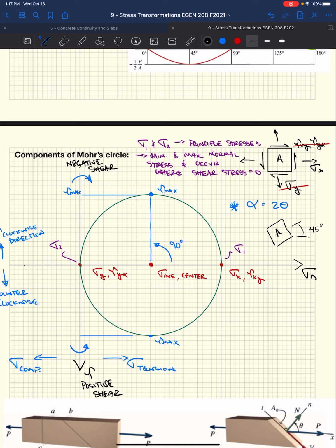And also at this point, we have a normal stress. It's got an x coordinate also. X coordinate is the same. So we're going to have a normal stress on the x face and a normal stress on the y face as we rotate these 2 points over. In this case, we're going to have a tension stress on both faces that are equal to essentially the average stress. The stress is the halfway point between our initial maximum normal stress, and then we had 0 on the y face.